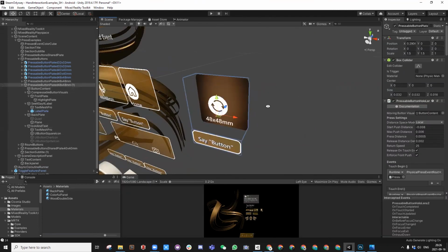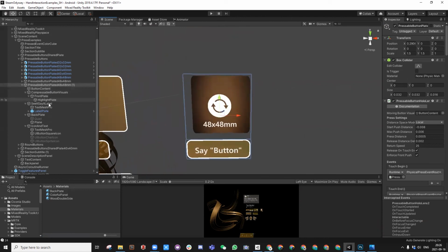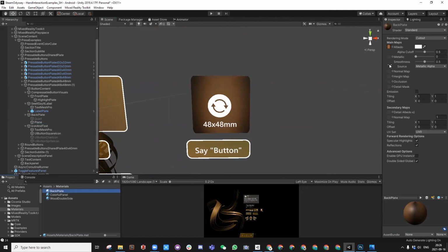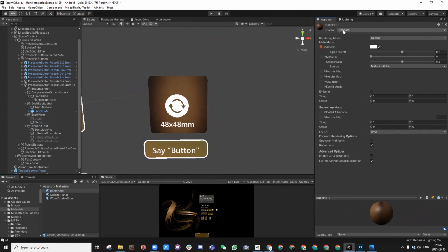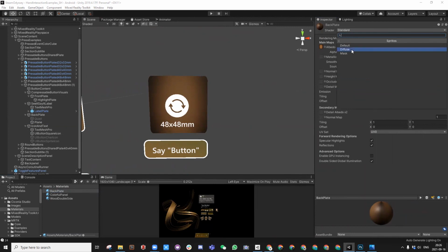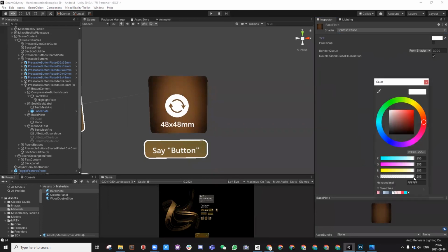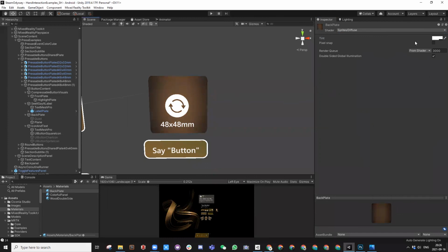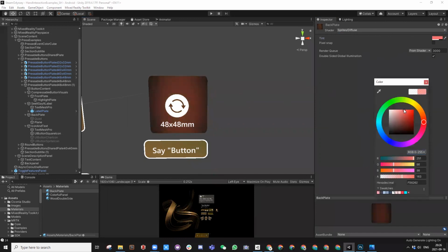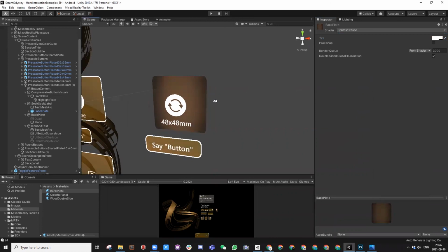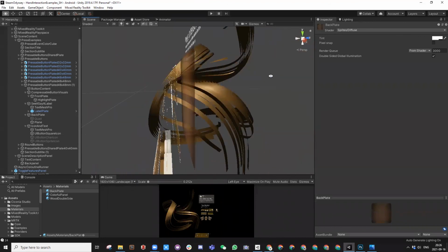And if you want to make it transparent and also have a cutout, you will need to update the material. You shouldn't use the standard material, but you can use sprite, and you can use diffuse or default, but diffuse this time. And we can just change the opacity of this color. In this shader, you can also have some kind of tint on this material as well. But that's totally up to you. You can add transparency as well as having the cutout. Okay.